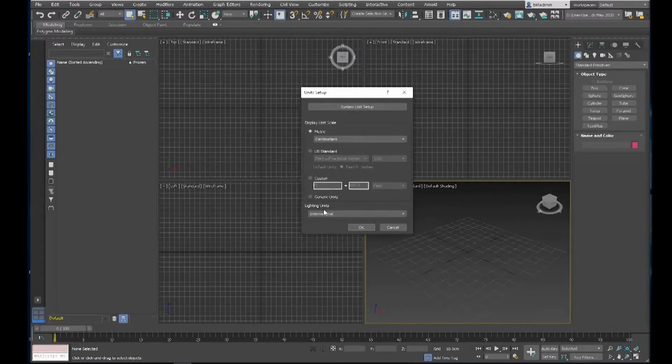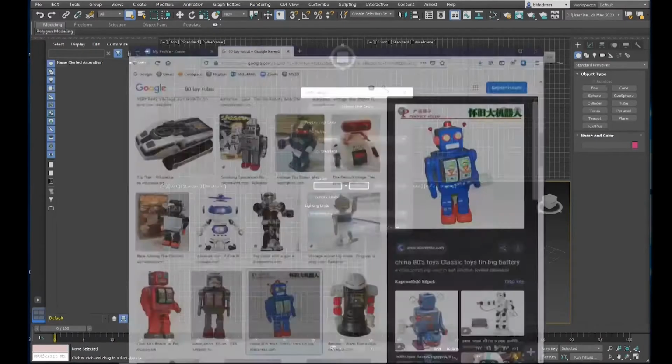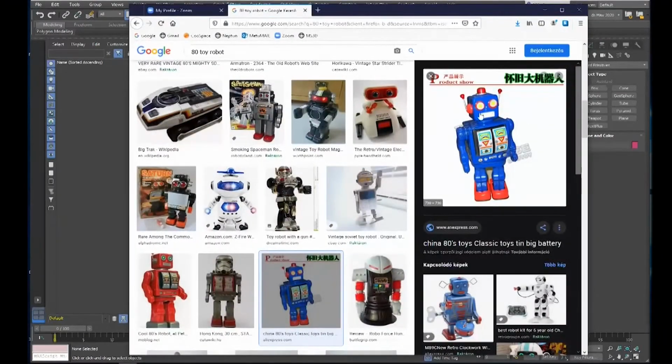And your setting is about you choose the generic units. Generic units is usually referred as 1 meters. So 1 generic unit is usually 1 meter in games. But depending on the convention, you can use different one. For standard modeling, it's good if we are using metric units, and I would choose centimeters because it will be a robot head. So don't forget, this will create something like this.